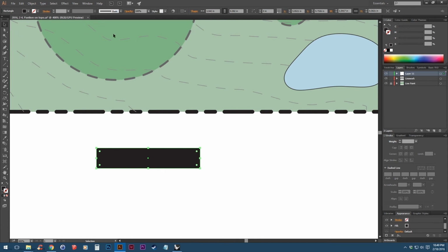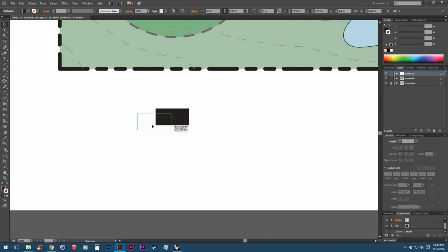going to draw a rectangle, then I'm going to go up to the sizing here under the width and the height. For the width I'm going to set it to 0.5 and a height of 0.25 inches. So this is going to represent half an inch or 8 feet. The next one I'm going to copy down to this corner.